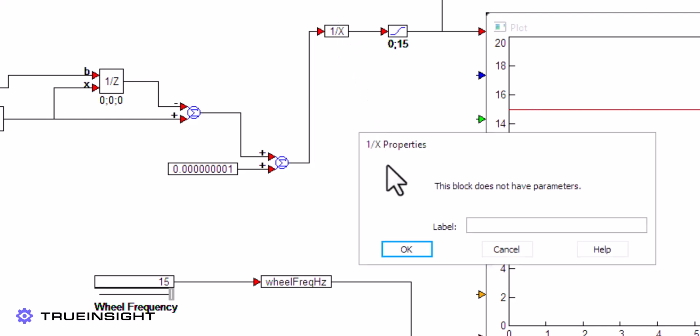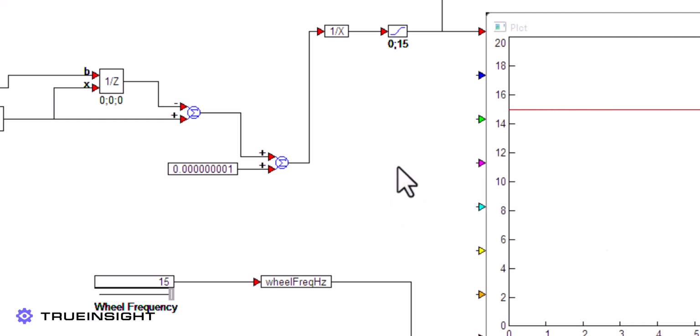encoder signal. You will also notice that we add a very small value to the period and calculate the inverse. The small value is to ensure that we do not divide by 0 when inverting the period, which provides us with the measured frequency of the encoder wheel in Hertz.